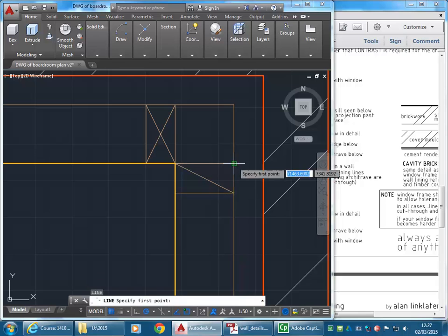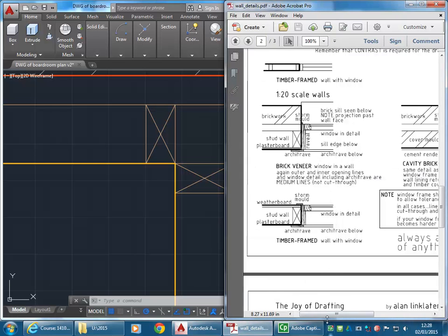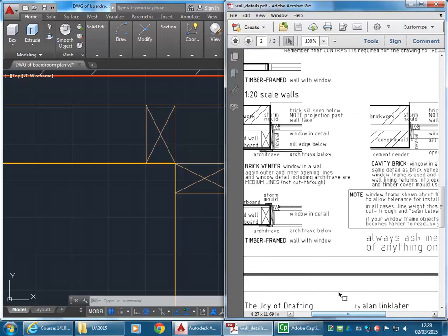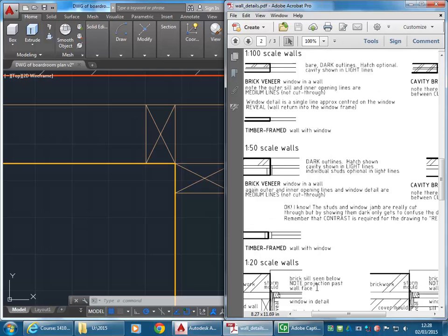When you say you work out where to go based on how the construction works, how do they stagger stuff across a long wall like this? Is it just based on plasterboard sheeting and mostly bolted in? Yeah. So the 450 spacings is okay. You can go to 600, but 450 is good. I don't think there are any notes here about that.